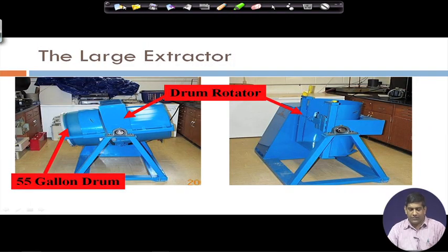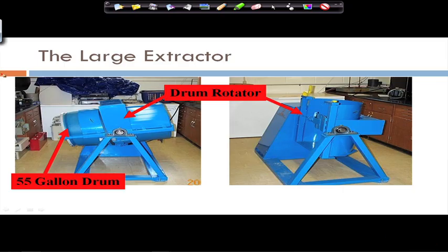We had a chance to get this drum rotator made, which was used to do the TCLP test in a big container, with the same rotation as required for TCLP, the same revolutions per minute. We also tested some samples where we did TCLP on this drum rotator as well as on the regular TCLP rotator, and the data was more or less in a similar ballpark. So we decided that we can use that, and we reduced the RPM as well. Rather than using 32 RPM, we reduced it to around 23 or 24 RPM, if I remember correctly, and that also worked out to be okay.